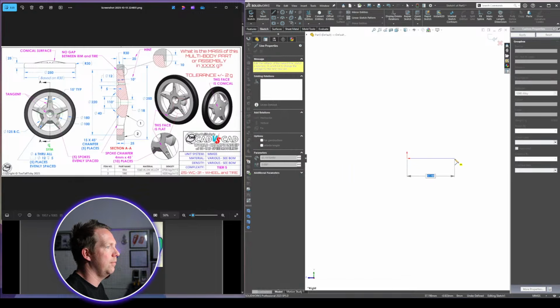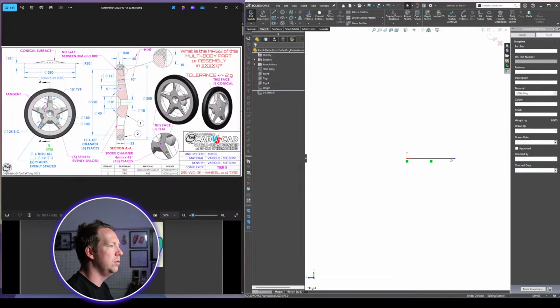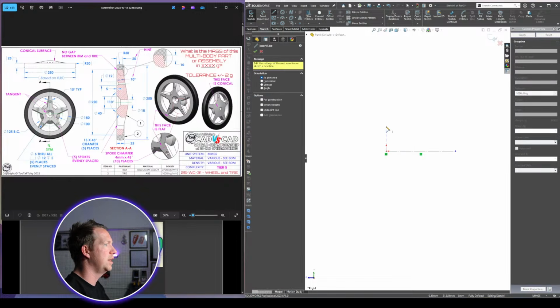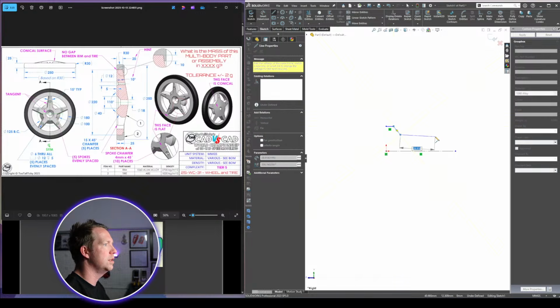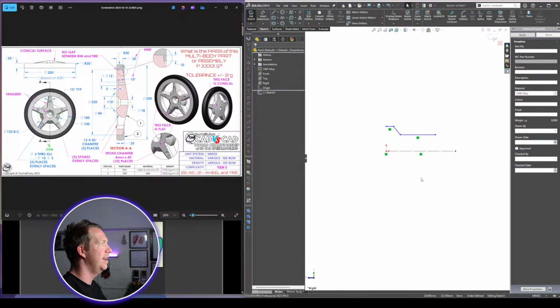Very first up, I'm drawing out a line in the middle, which is going to be my center line. It's good to get that center line in because we want to use some of these double dimensions so we can do the full diameter up and down. And then, funnily enough, my first sketch was this, to get that little section in the middle where the hole is. I don't want to do that in a hole wizard later. And I saw Arte say in your attempt, you've done a couple of cuts to get the angles and everything there. You just put it in the revolve straight away.